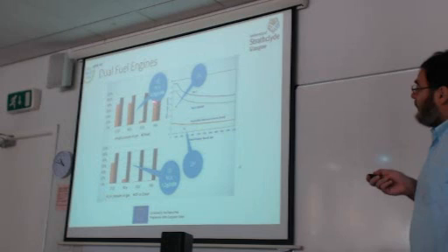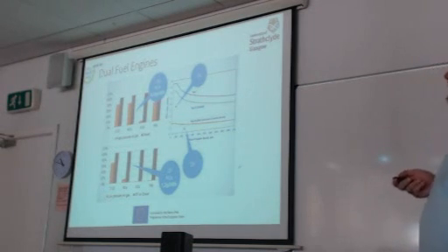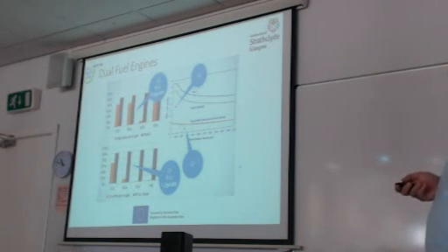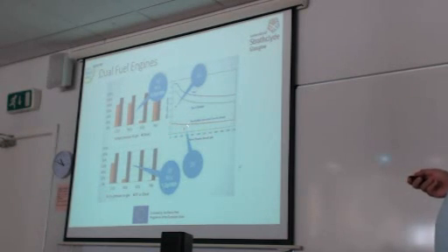And as far as particulate matter, which means unburned carbon, is concerned, we have actual elimination of particulate matter in the case of dual fuel, as the pilot fuel is only 1 to 3% of the total amount of fuel. And here there is a 20 or 40% decrease in particulate matter in the case of gas diesel engines. So if we see the operating points as far as NOx is concerned, gas diesel engines comply with Tier 2.